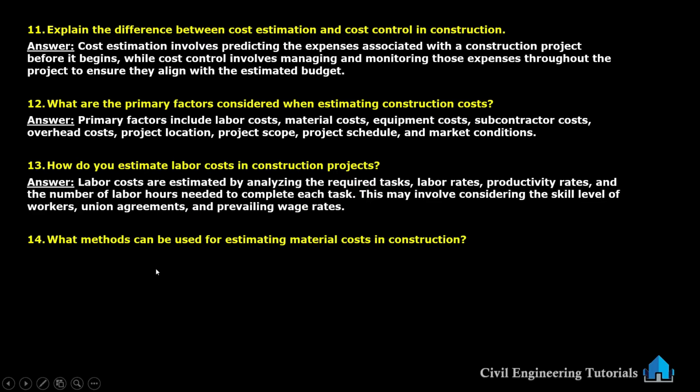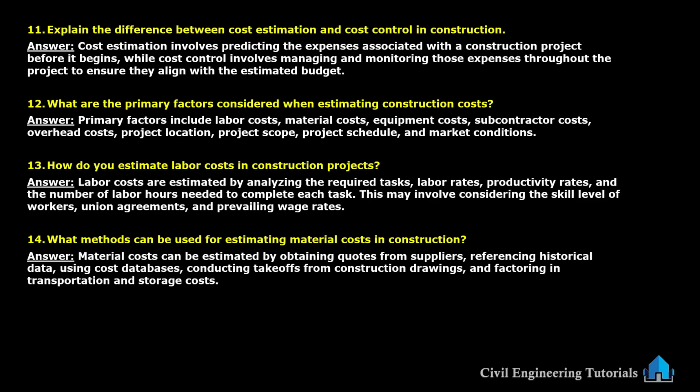What methods can be used for estimating material costs in construction? Material costs can be estimated by obtaining quotes from suppliers, referencing historical data, using cost databases, conducting takeoffs of construction drawings, and factoring in transportation and storage costs.